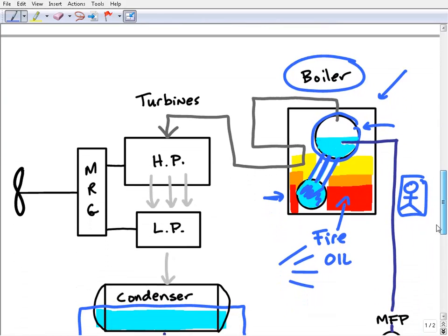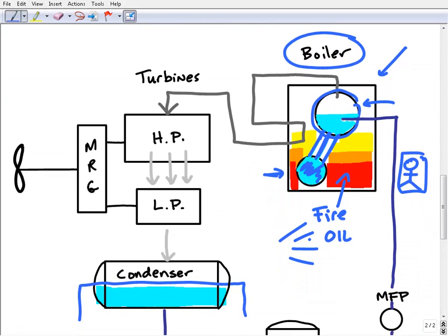All right, so here's our boiler. It's our heat source, right? We're spraying in some sort of marine diesel fuel. We're atomizing it, kind of like spraying it like a spray can, and it's burning just nice and toasty here. We have our water, and now these tubes right here are getting hot, obviously, right? And it's creating steam, okay? So our steam is bubbling up through these tubes, and eventually it's going to escape up here in our steam drum.